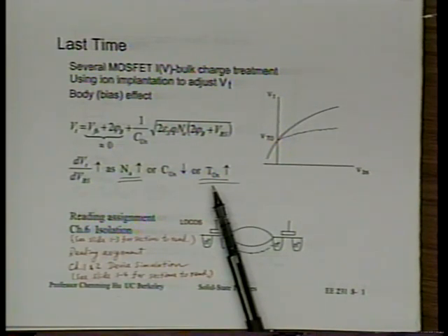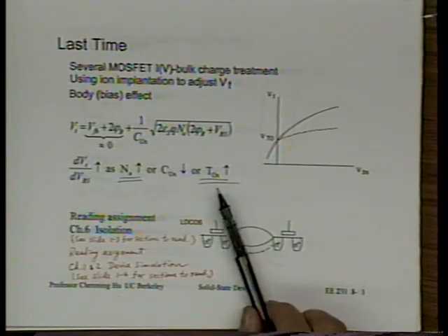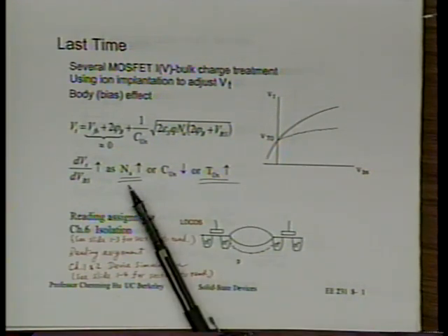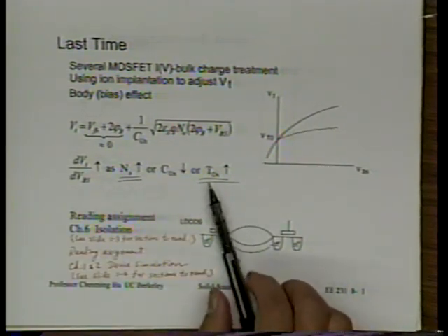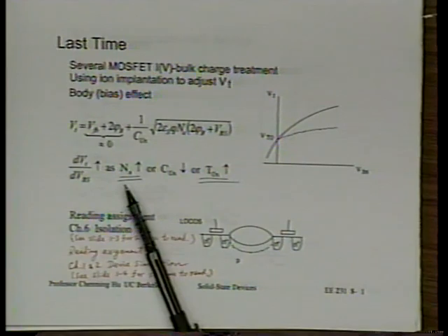By the way, do you know when we see a combination of thick oxide and heavy doping of the body? When do we see that combination? Maybe this will give you a hint. First, ask this. When oxide is thick and the doping concentration is large, what kind of VT are you going to get? Do you get a large VT or small VT? Large VT. So basically, when you have a large VT, you get very large dVT/dVBS.